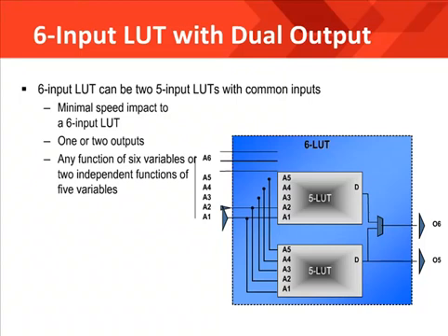This is highlighted when you consider what you would get if your combinatorial logic had 7 inputs. Because the LUT has 6, your synthesis tool would be required to add a second LUT in series with the first. This would then dramatically increase the delay associated with this path and cut the maximum frequency possible.